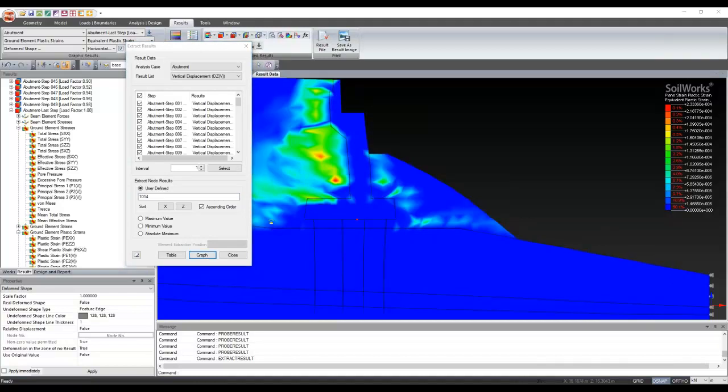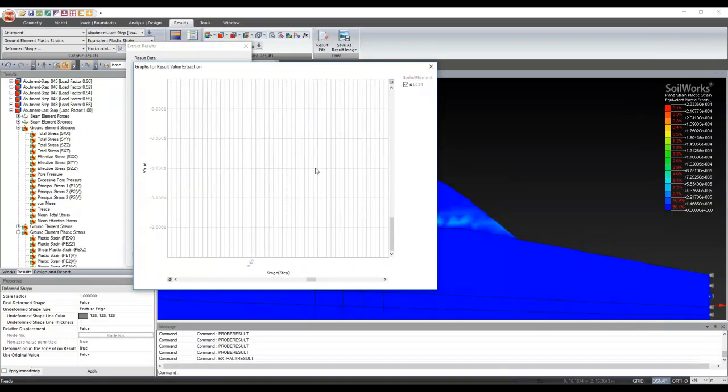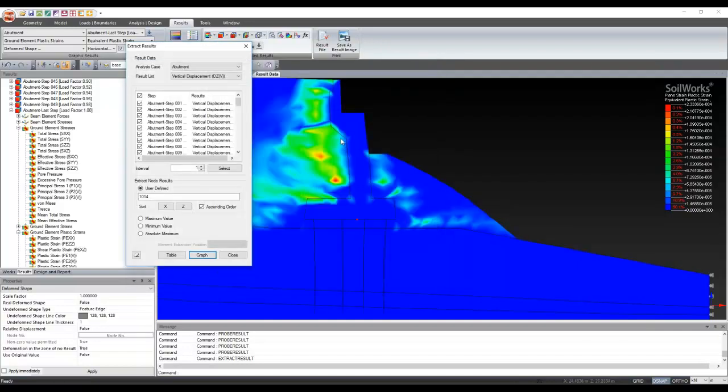Yeah, this is how it is almost linear. You can see it's almost linear, but it's not completely linear, based on the number of increments. If the number of increments is even higher, you will have the non-linearity coming into the picture. You can even export into Excel. And similarly, you will have your nonlinear behavior based on the load coming from the superstructure, and the soil can behave as linear or as nonlinear. That depends on the load. So you can draw the stress versus strain behavior.